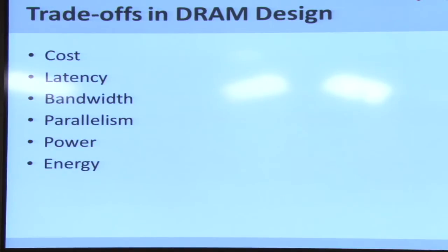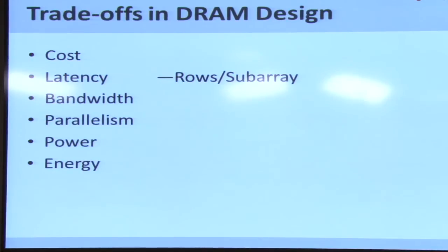Anyway, he's right. He has read the tiered latency DRAM paper, which essentially describes this trade-off, right? The number of rows you have within each subarray in some sense dictates how long your bit line is going to be. And the reason that is the main factor is because the bottleneck for DRAM latency today is how fast the sense amplifier can drive a specific voltage level on the bit line.